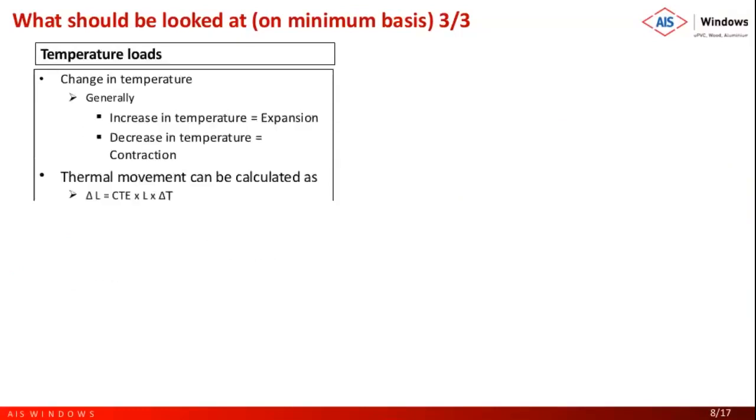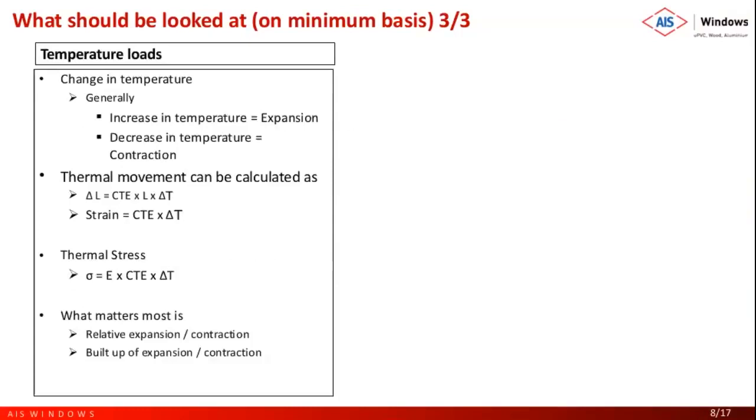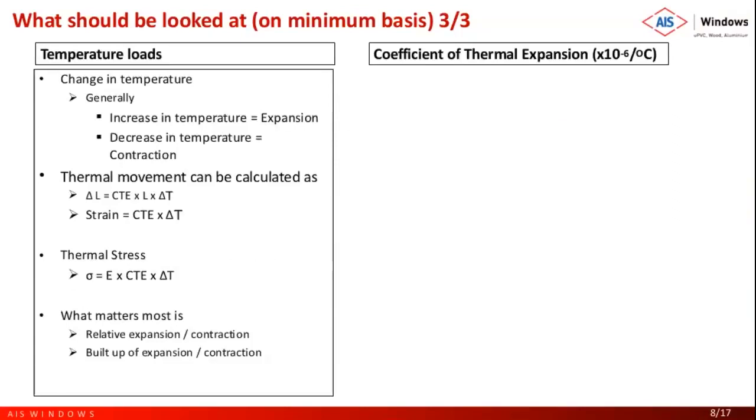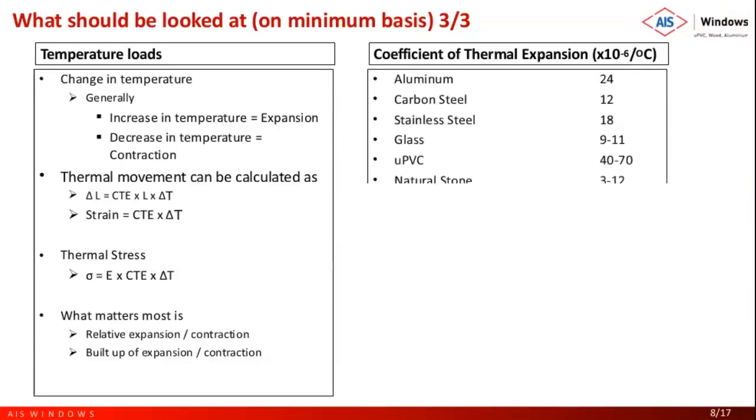So first was gravity load, second was lateral load, and third, which is most important. So gravity load, like I mentioned, is where we can estimate fairly accurately. Lateral load, it is all statistical based approach. So there are always chances of errors. It can be higher, it can be lower. Temperature load. Now temperature load falls in between gravity load and wind load. Although we know what is the kind of change in temperature can happen, but this can also be a probability theory.